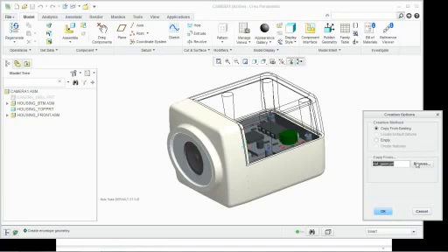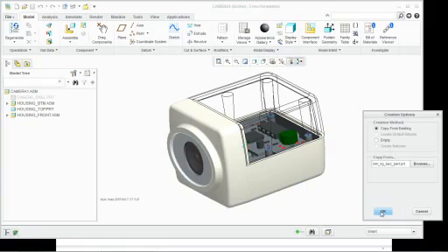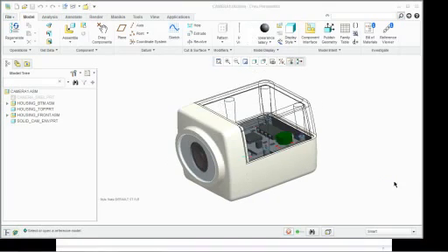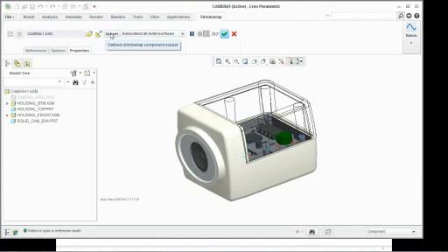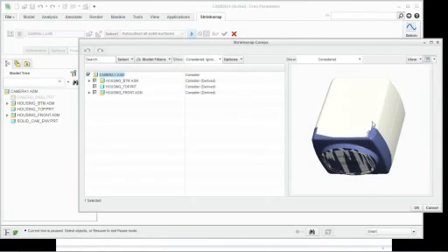So I want to copy my geometry from, let's see, milligram, kilogram, second. Where are you at? There you are. Milligram, kilogram, second, .prt. Click OK. And yeah, go ahead and click OK there as well. So now I'm going to click my subset button, and I'm going to actually select which components I want to keep.